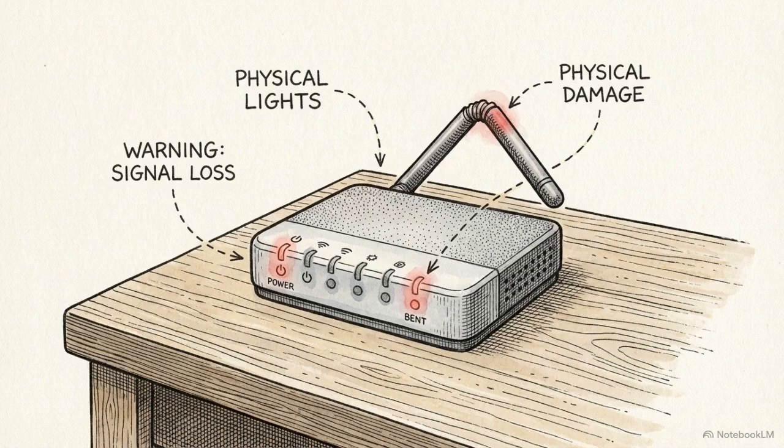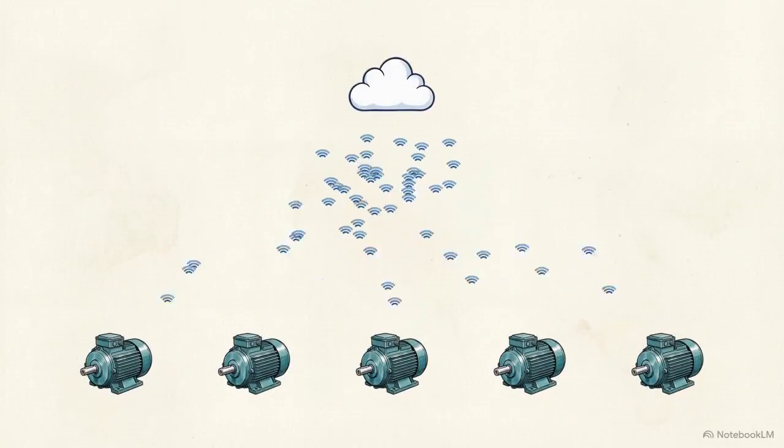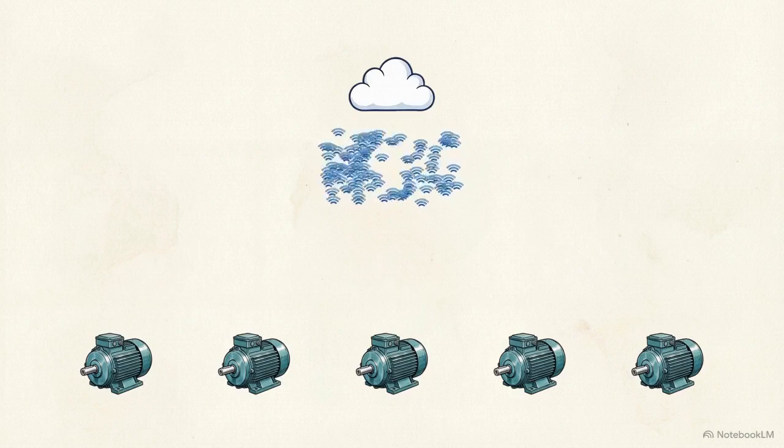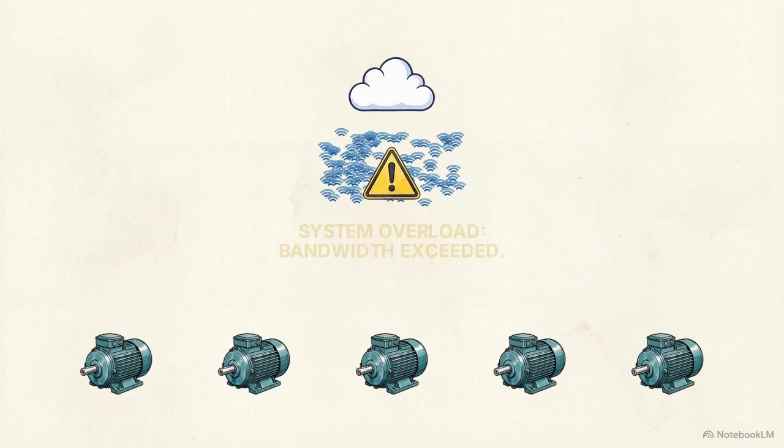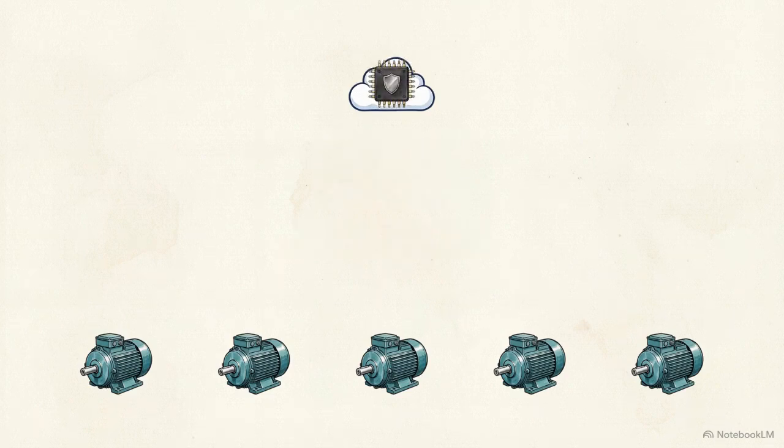While multimodal fusion provides high diagnostic clarity, it creates a severe data throughput problem. Generating continuous, high-frequency raw data from multiple sensors rapidly overwhelms standard industrial networks. Sending raw, uncompressed vibration and acoustic waveforms from hundreds of factory sensors directly to centralized cloud servers is mathematically unscalable. To eliminate this bandwidth bottleneck, engineers move the initial data processing out of the cloud and relocate it directly onto the physical casing of the machine.